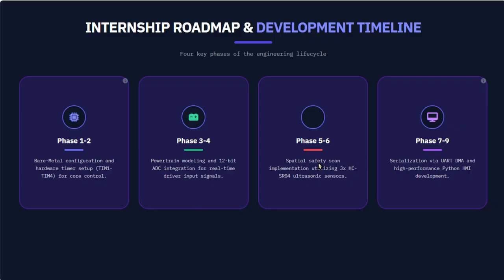And phases 4, 5, and 6 move into the active safety layer. I drove 3 distinct ultrasonic sensors to run simultaneously, scanning around the perimeter, with vehicle-managed distance logic along with the fault management rules.